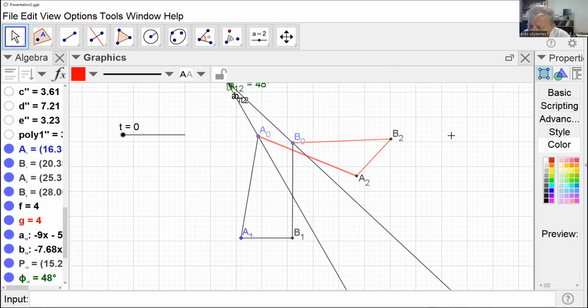A1B1 is equal to A2B2. Why? It is a rigid body that we are discussing. A1B1 and A2B2 correspond to the same segment AB on that rigid body, so it is the same. A0A1 is equal to A0A2. Why? Because A0 has been selected on the perpendicular bisector A12. Any point on a perpendicular bisector is equidistant to A1 and A2. Any questions?